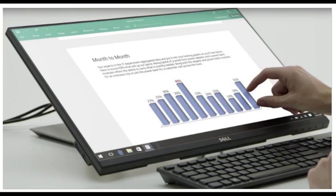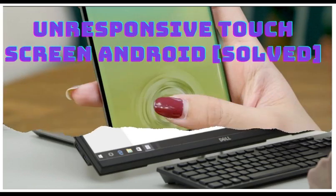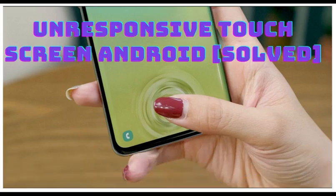A resistive touch screen panel is coated with a thin metallic electrically conductive and resistive layer that when touched causes a change in the electrical current, which is registered as a touch event and sent to the controller for processing. Resistive touchscreen panels are generally more affordable but offer only 75% clarity, and sharp objects can damage the layer. Resistive touchscreen panels are not affected by outside elements such as dust or water.